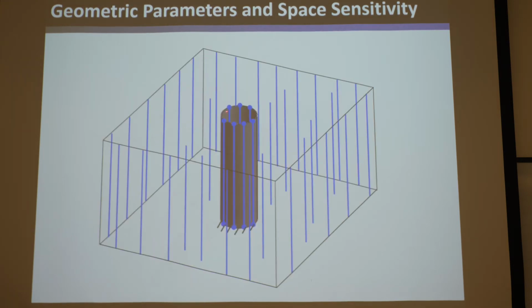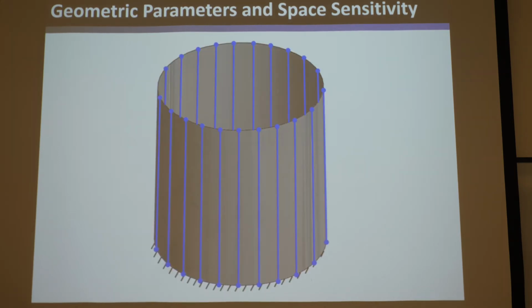You know, when this is super, super thin, you say, okay, it's going to be a wire. When it's about this, it's like, you know, it's about that. And when it's large enough, then it's basically no degrees of freedom. Okay? And you can start quantitatively putting numbers on this if you put the same size bodies on both sides and do the modal analysis and see what natural frequencies come in what orders and that kind of thing.